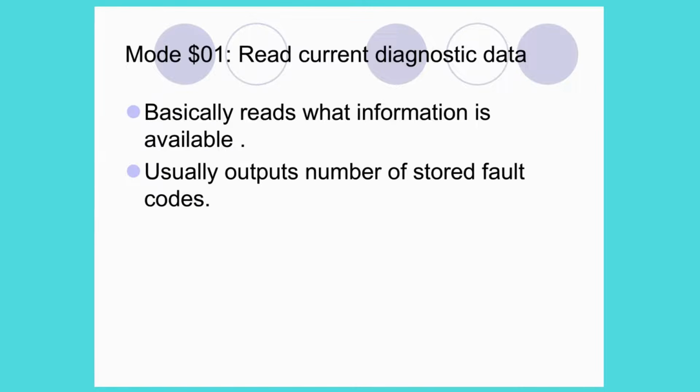Mode 1. Read current diagnostic data. Basically reads what information is available in a controller, usually outputs the number of stored fault codes.